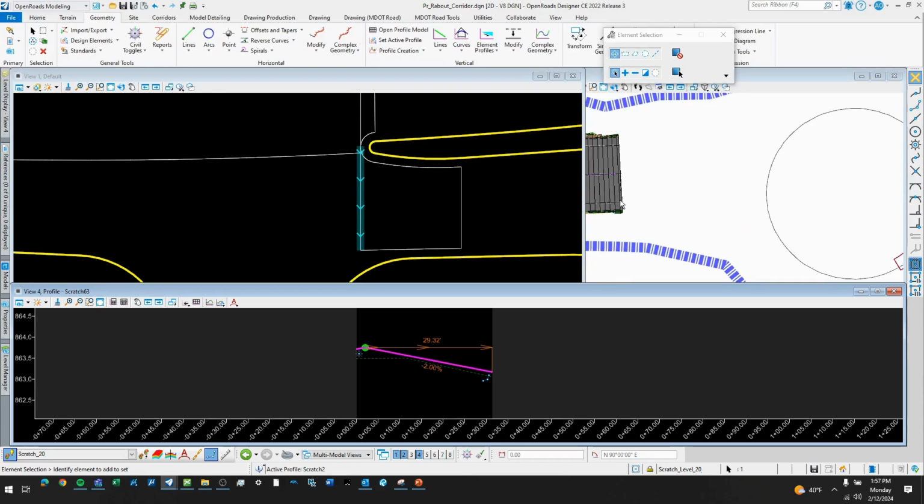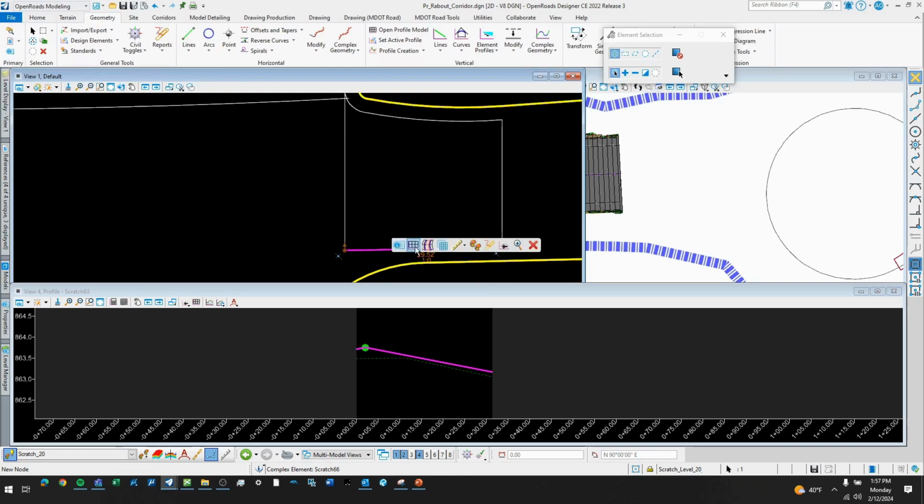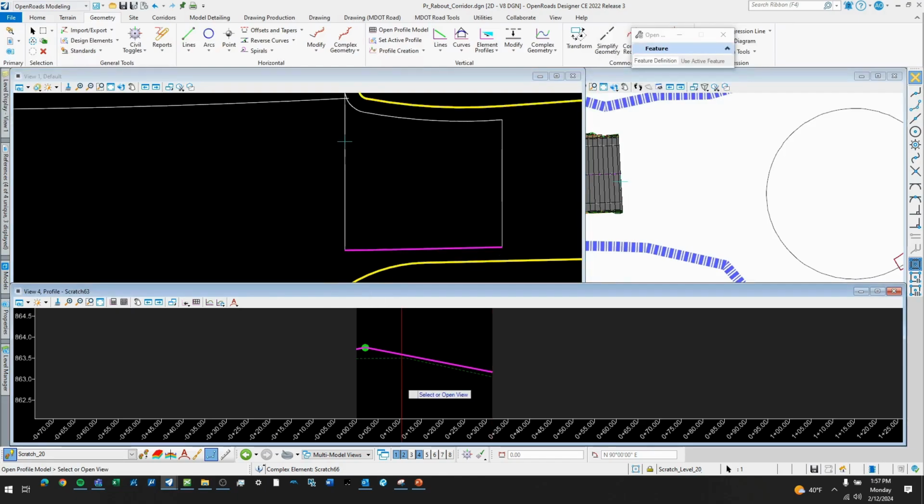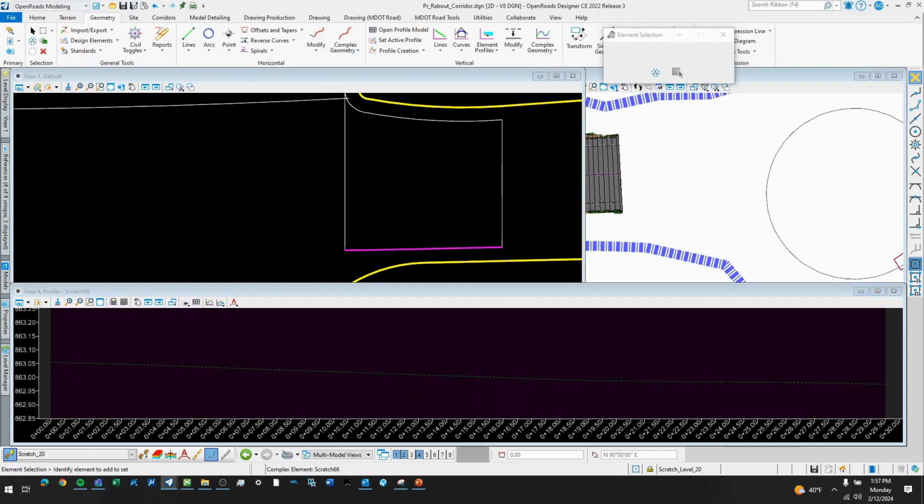So now this line is kind of mimicked. Can't really see it there, but from here, this is part of that reason we want to continue that 0.4 or 0.3% slope, to show up that 0.3% slope that's going down. And you can't just map this out at 0.3% because there's a lot of curvature and stuff like that going on. This one's pretty straight in terms of that edge line, so I'm just going to get that profile intersection point.